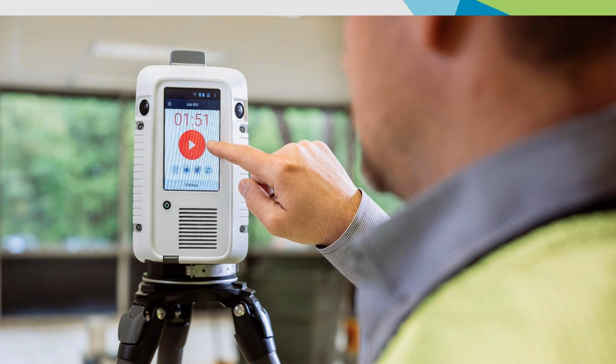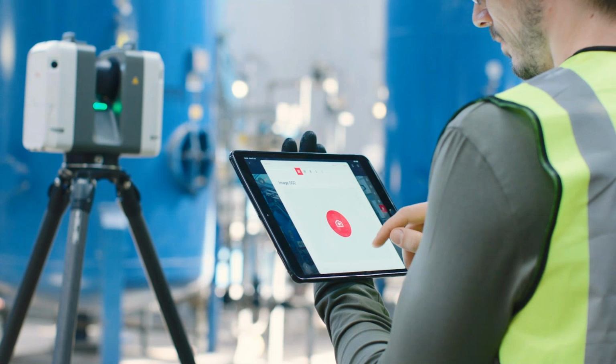So as I said before, the tablet, the Cyclone Field 360 application is completely optional. So here you can see the user is just setting up the instrument, choosing the scan resolution, whether they want to take images or not, whether you want to use our VIS technology or not, for example, or take a double scan function as well. We can do that on the RTC 360, and you can just hit the play button on the side. Then you can piece the data together back in software if you want to, but the option is there to use it in a standalone fashion if you want to. And then we've got the option to use it with Cyclone Field 360. So this is now just going to play a short video, just showing the use of the RTC 360 by a piping designer in the environments that we're going to be talking about today.